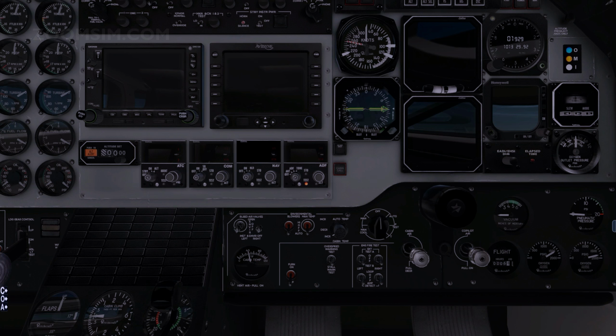Two fans, one acting as a blower, the other as an extractor, ventilate the avionics. The vent blowers are controlled by a 3-position switch, placarded high, off, and automatic, and the mode control switch. The blowers operate in the high position when the mode control switch is in any position. When in the automatic position, the vent blowers will operate at low speed when the mode switch is set to any position except off. Blower control is independent of all other components of the environmental system.